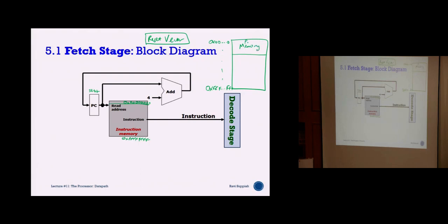My program memory, or instruction memory, because that will not change. That is permanent, it's fixed. So when I reset my system, I go to address 0, take the first instruction, and start executing. No matter what happened, when I press the reset button, this will always start, because I know I need to jump to address 0 and start executing the first instruction.